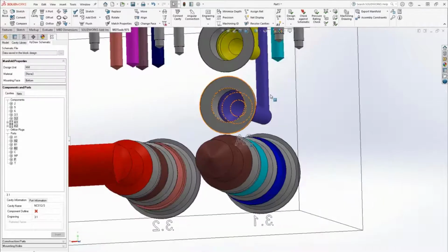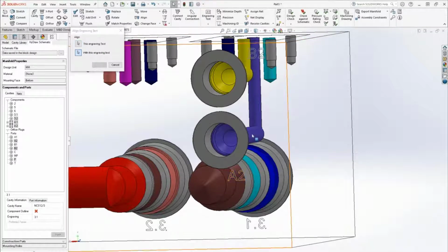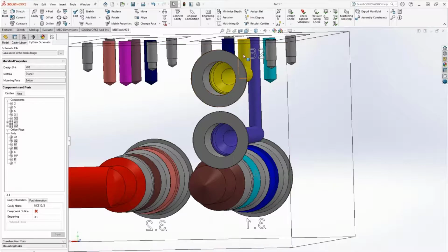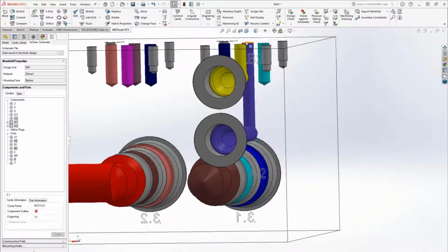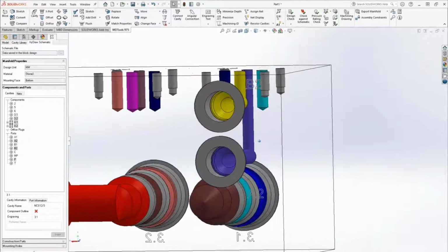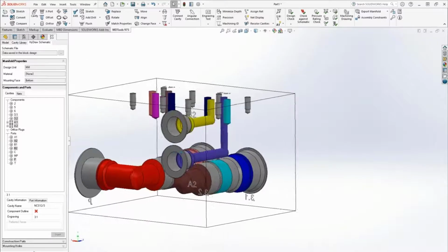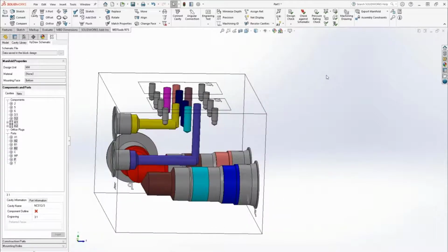It is also possible to align engravings. We can use the align engraving command to select an engraving and align with the other one. The align command will not ask the direction. It will align, in this case, on the X, because it's the shortest distance. So it will just compare the position and make the same X or Y according to which is the minimum distance between the two engraving texts.